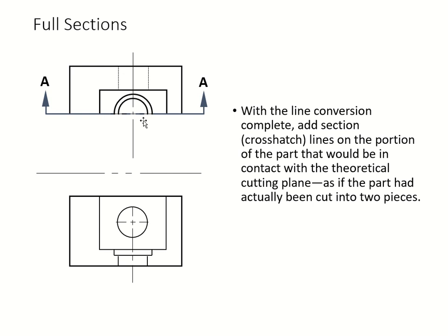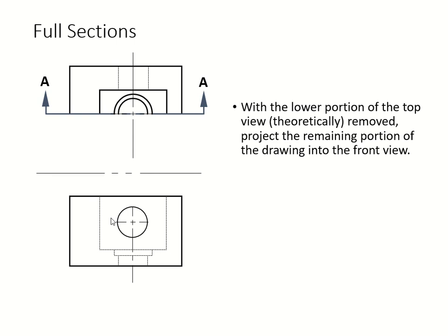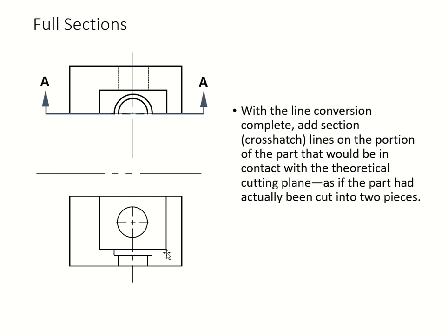So my reference plane, or the front view, is going to capture this cut area, this exposed area, so we can see the internal features now. So they became visible lines. It was a hidden line before, now visible lines. So we change our front view according to our cut.